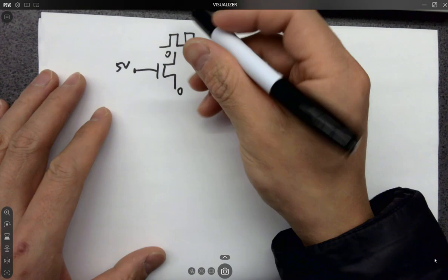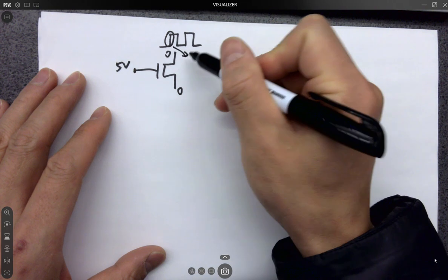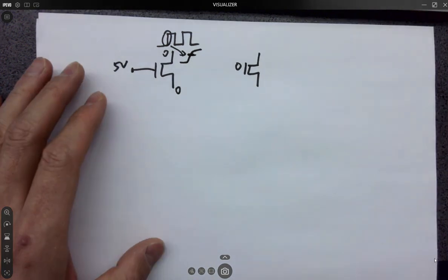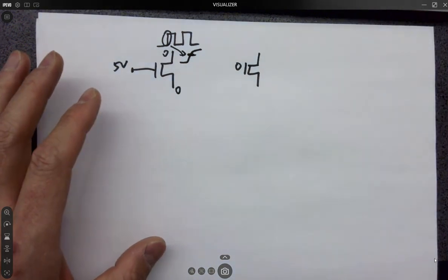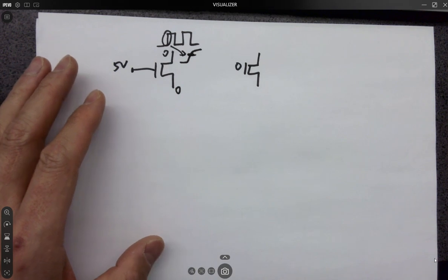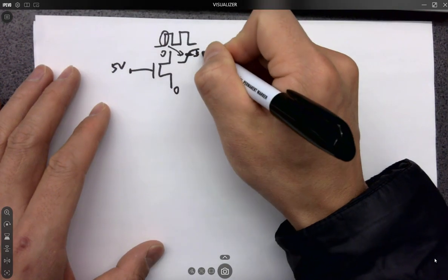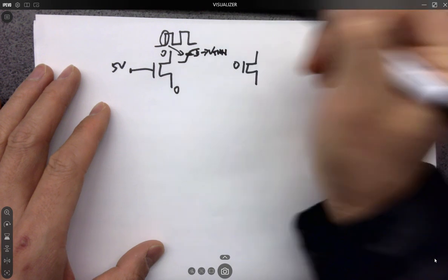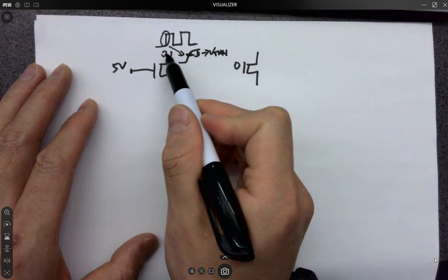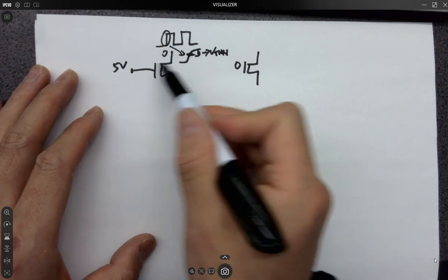So if you have 0 volts here as well, no problem. Until when do you see a problem? When this voltage, if we zoom in here, is going to be a ramp, like this. Whenever it rises to which point, you have a problem passing it? It's going to be VDD minus VTHN. So this little range here has to be VTHN. Why is that? Because your gate to source voltage difference becomes VTHN. Can that be smaller? Whenever it's getting smaller, it shuts off.